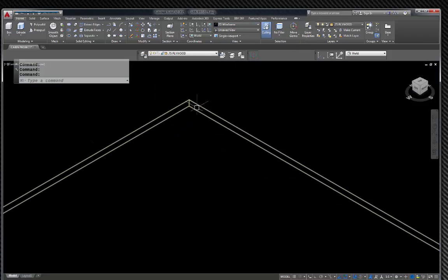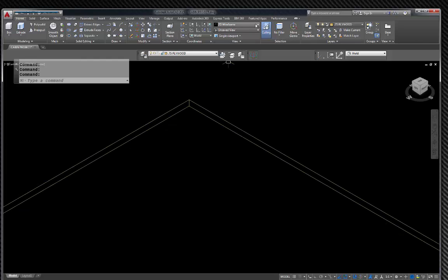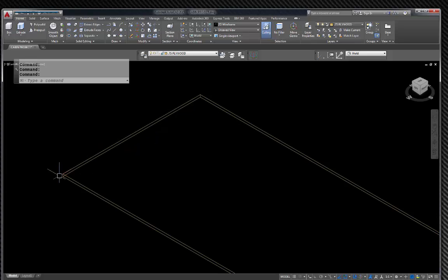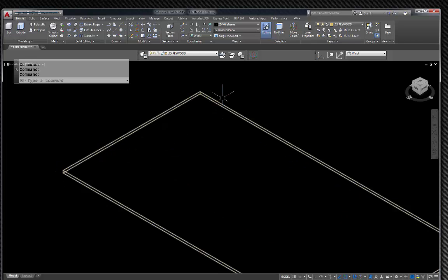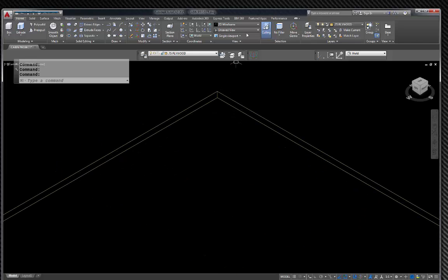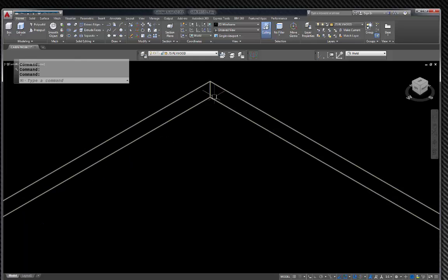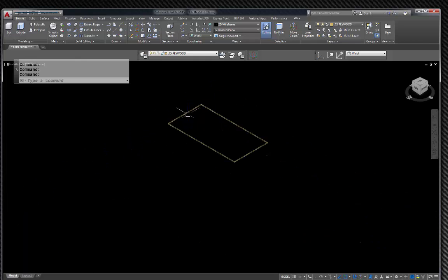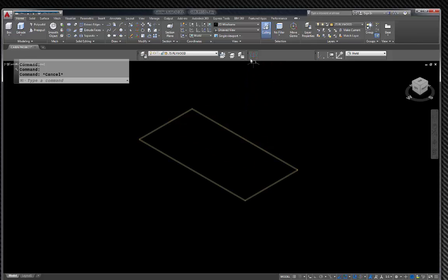The reason is, when you're in a shaded color, it's harder to find points on your geometry. It just is harder to find. So if you work in 2D wireframe, it really helps you be able to reach through the piece and select a point on the back side. Okay, so there's my first piece of material, and that's all I need for right now.